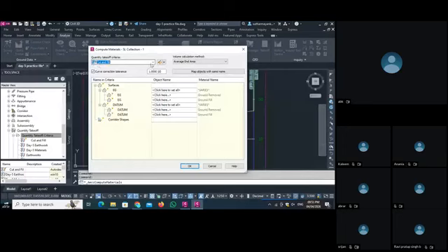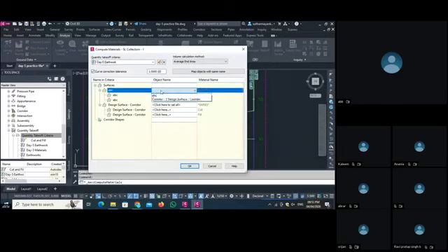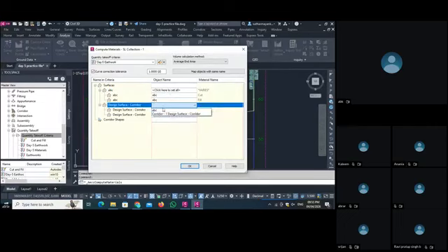Now you have to select the takeoff criteria. I have to do the earthwork, so I create one design criteria here. So I select the day 5 earthwork criteria that I created. Then in the surface, as ABC surface, I have to select ABC surface, and for the design surface, I have to select the design surface, corridor surface.